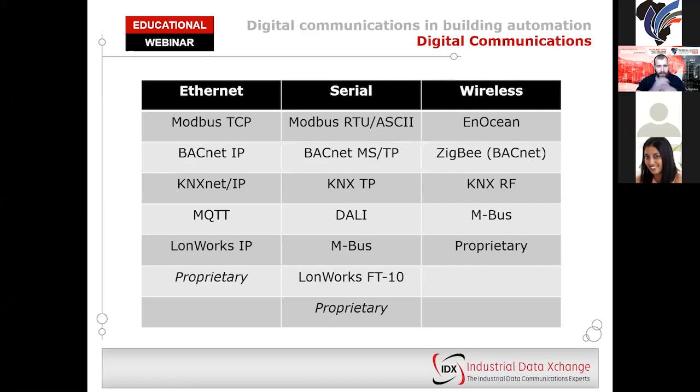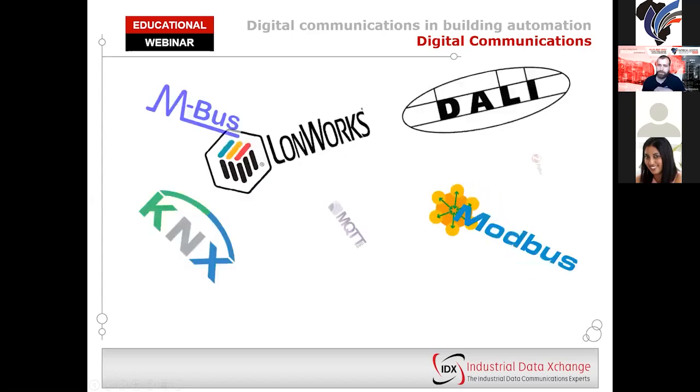And you even get a version of KNX called KNX PL, which stands for KNX Power Line, which actually uses your existing power infrastructure in your building and superimposes a signal onto that power line to connect KNX devices. So you don't even need to run KNX wire between those devices. Many different options depending on what you would like to do.